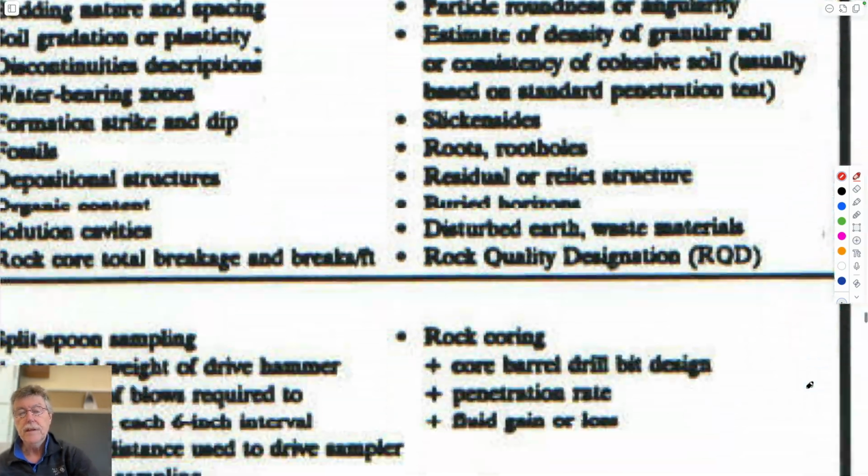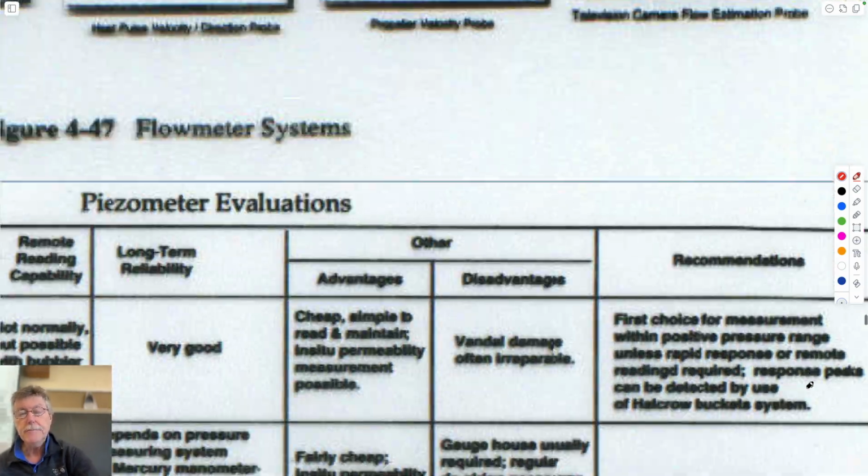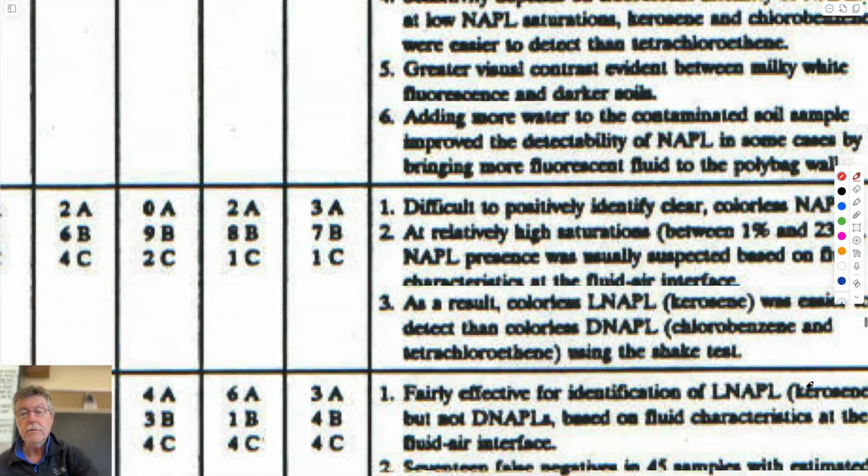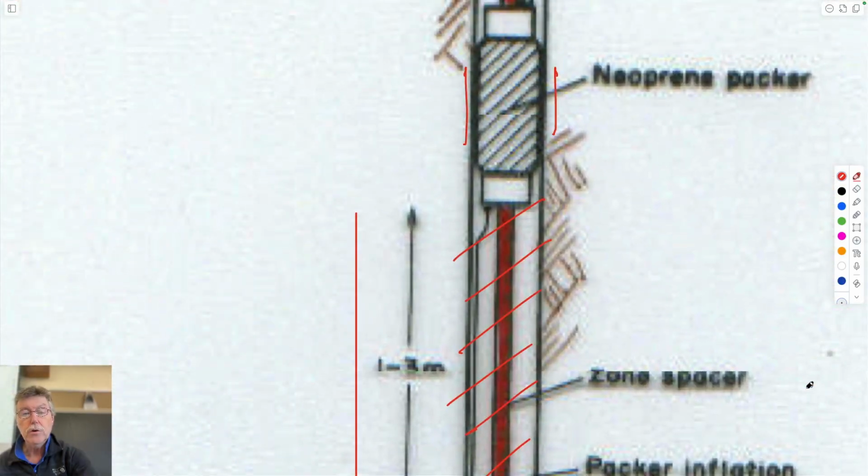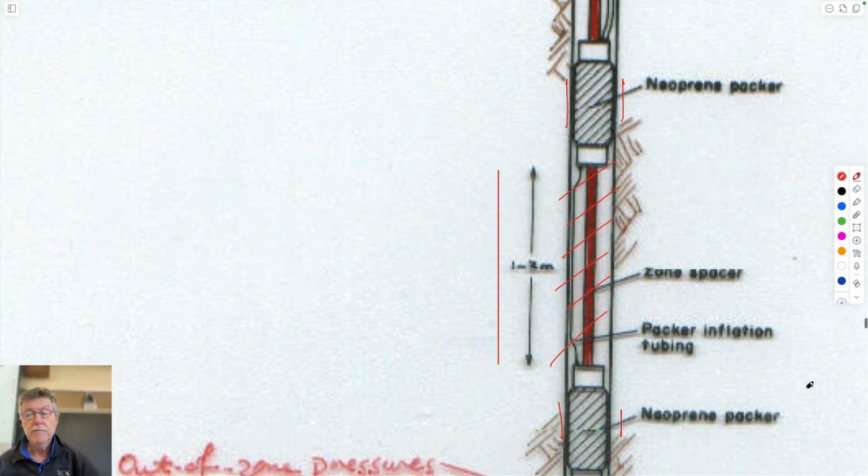The only difference from doing it here is that this is doing it in a place where every time you do this experiment, it's exactly the same location in the borehole. If you do it with a straddle packer, then you can do it at the bottom of the borehole, and then you can work your way, if you wanted to, all the way up the borehole to places of interest that you might be in to be able to make that same measurement. You can also come back and re-enter it and go back to the bottom and just repeat it.